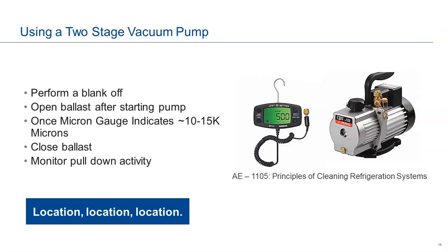Where you have your rig and you're putting your Micron gauges, you want to make sure you keep your Micron gauges clean. So you want to put it in a port where it's not getting oil through it all the time. If for some reason you should get oil in your Micron gauge, there are things you can buy, obviously, but rubbing alcohol works real well, I found, okay? But be very, very careful on that, all right?